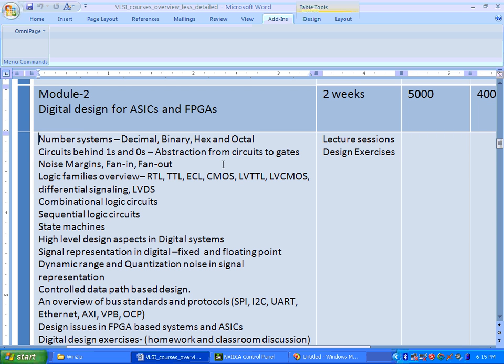For example, if you are only purely doing Verilog coding or VHDL coding, then you may not really bother about all this. Okay, but let's say you are not only doing Verilog coding. You are also getting into the backend. Then you have taken some backend library and plugged into your tool, which is generating the final netlist, final layout.